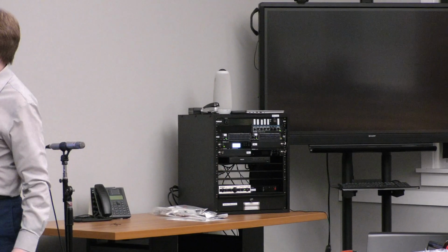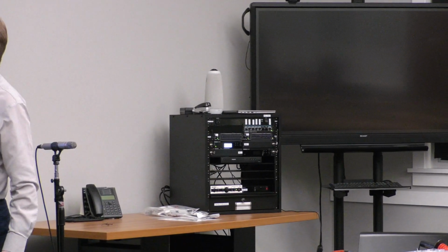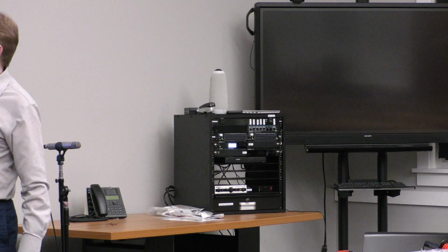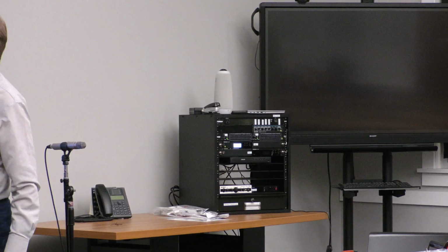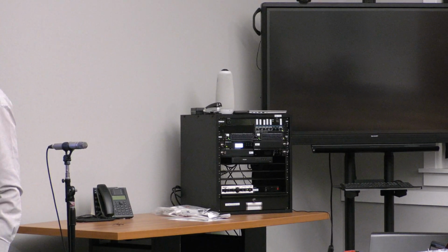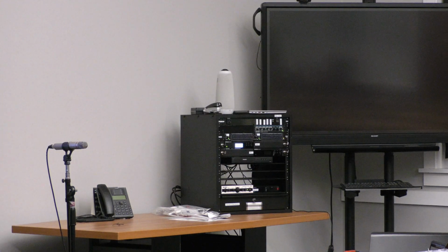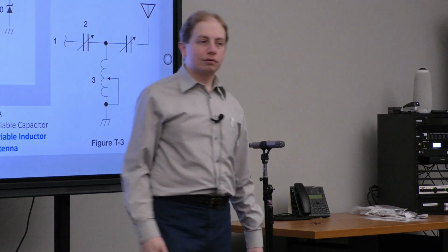Usually they're shown left to right on the schematic. This is actually backwards. This is showing a voltage source on the right. This Zener diode is acting like a voltage regulator. This is then allowing you to vary that voltage. This gives you an LED. You have a capacitor, a diode. Actually, they have the diode going the other direction, so this isn't really a practical circuit. But then they're transforming this up to a higher voltage to light a neon lamp, I guess.